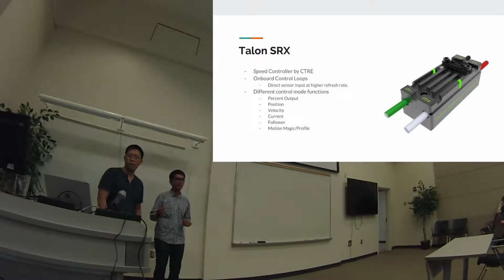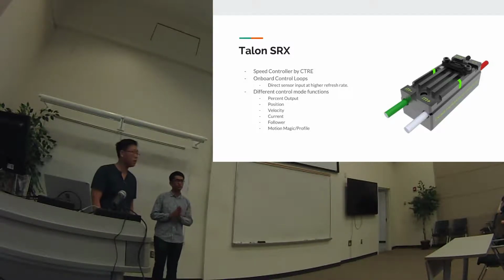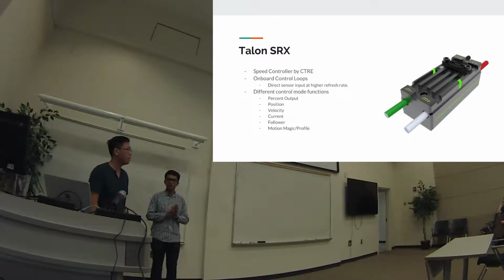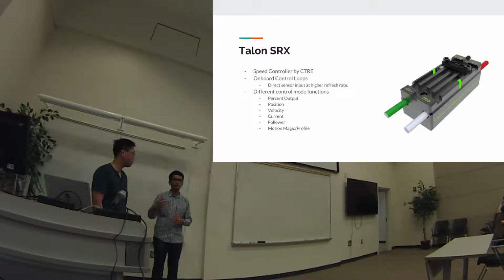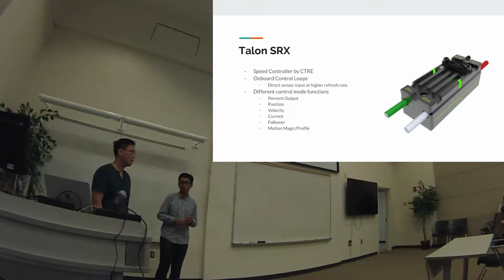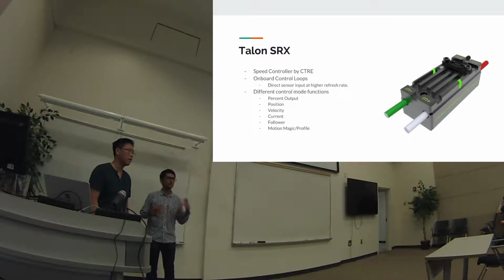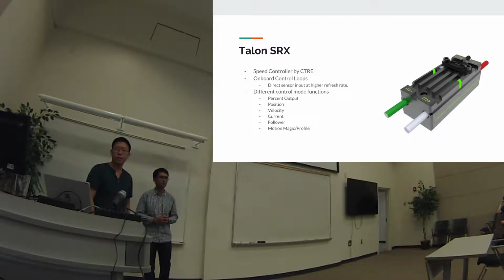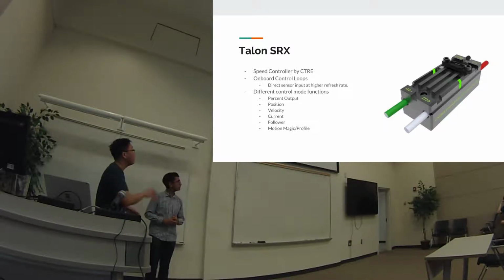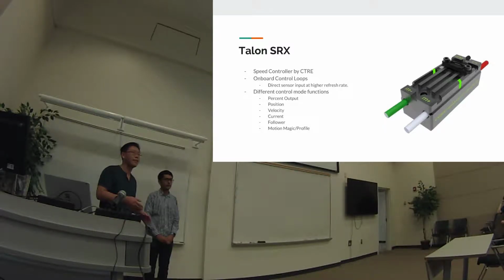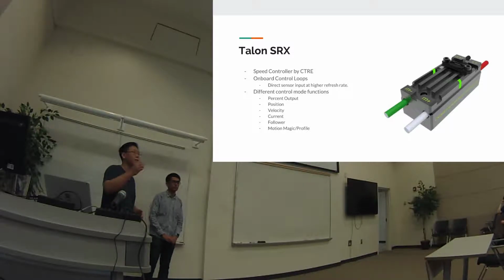And it's the same thing. And next we would also use motion magic and motion profiling, which we're going to go a lot into later on, but CTRE provides a really good way to do motion magic right into the code. Once you've tuned your PIDs and once you set your set points, you can use motion profiling really easily. Yeah, so just to clarify really quick, motion magic is just what they call their tool to automatically do motion profiling. And we'll go into that later.